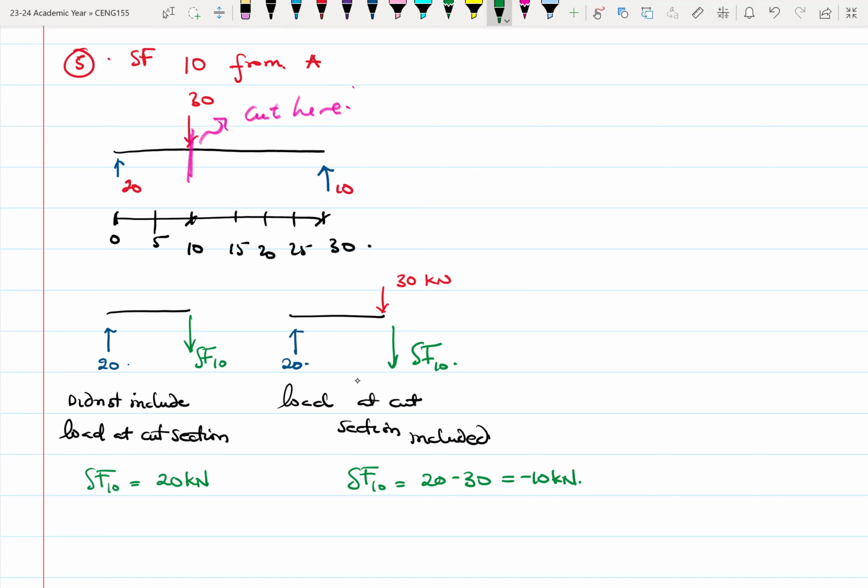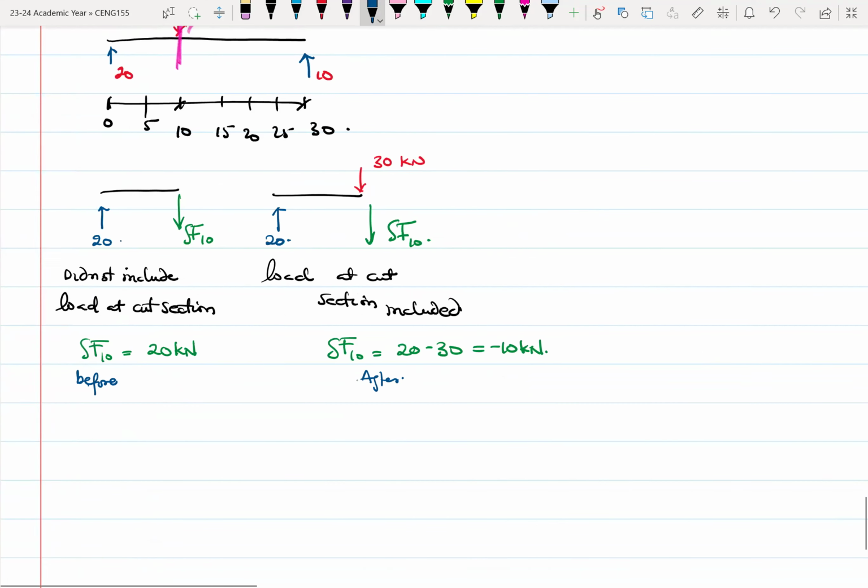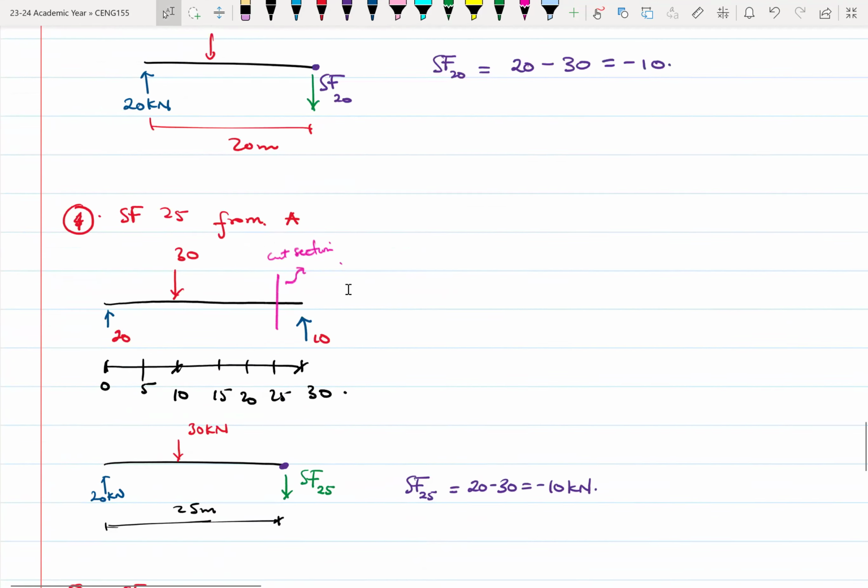And the only way we can capture that slicing behavior is by looking at the shear force value with and without that particular load. So here I can say shear force before and then shear force after, and they both are correct. Okay. For now, let's leave it this way. We'll come back and then see how things finally look in the end.